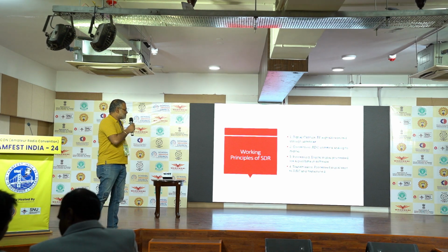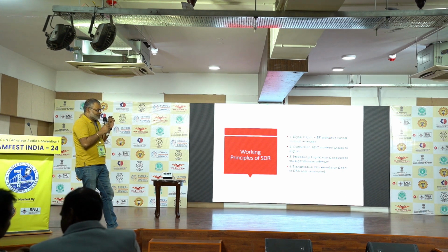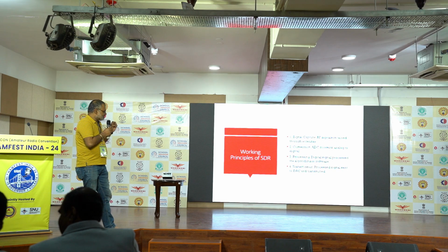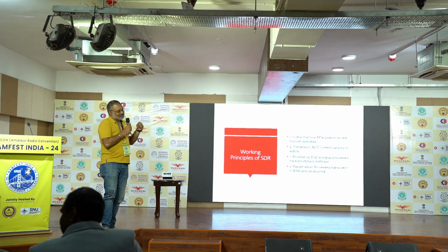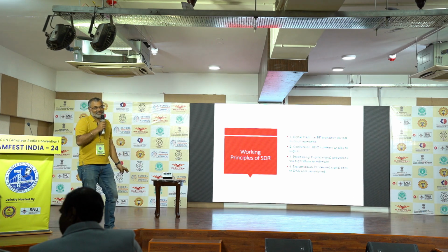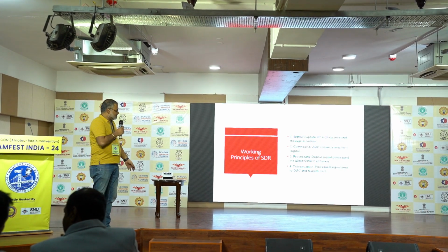Okay, working principles. RF signals received through antenna. Here the antenna is receiving the radio frequency signals. The ADC, the analog to digital converter, is converting the analog signal to digital. Then it is feeding into the software. Digital signal is processed in the software, and then the software is processing the signal and giving out the desired output through a digital to analog converter, and then what you can hear, or you can demodulate, or you can do whatever you want with the signal. Next slide.